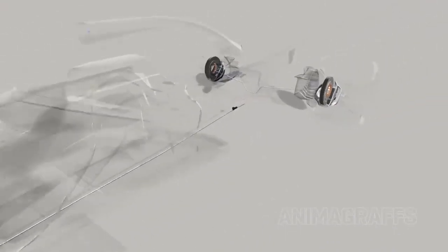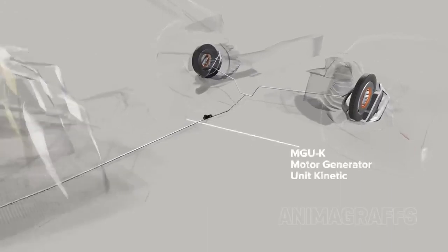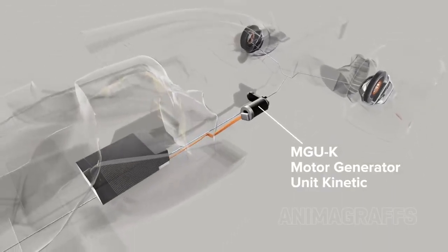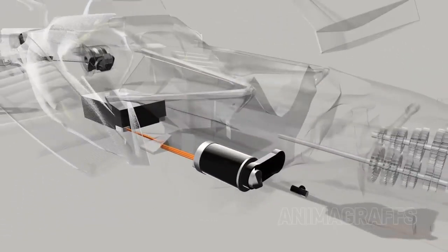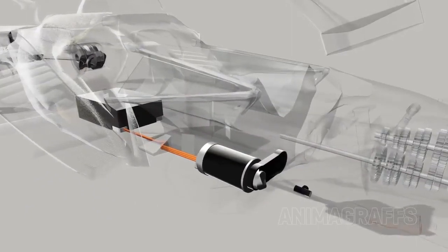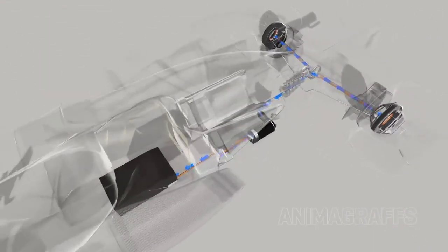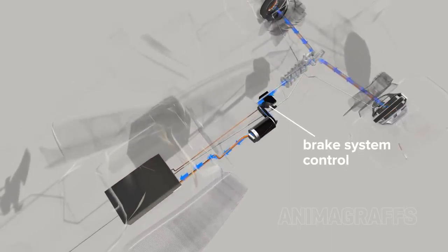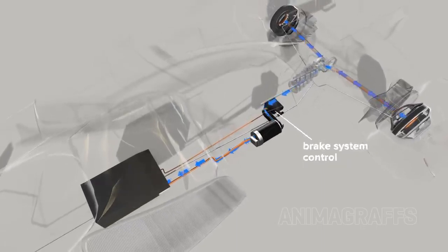The rear brakes have a similar design strategy, but have become smaller in recent years with the addition of the MGU-K, or Motor Generator Unit Kinetic. The MGU-K is geared to the crankshaft and functions as an electrical power generator to charge an onboard battery as driven by a portion of rear braking forces. A computer mounted inside the gearbox enclosure manages and balances this complex braking system.